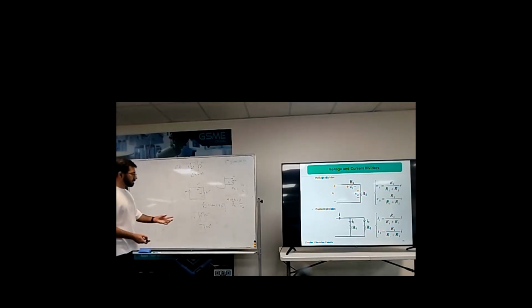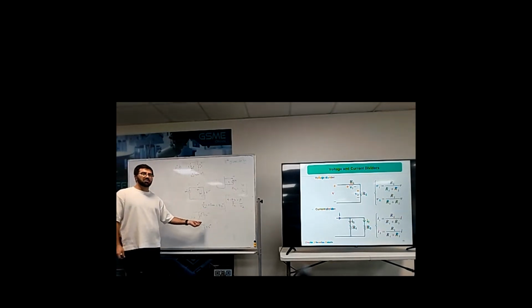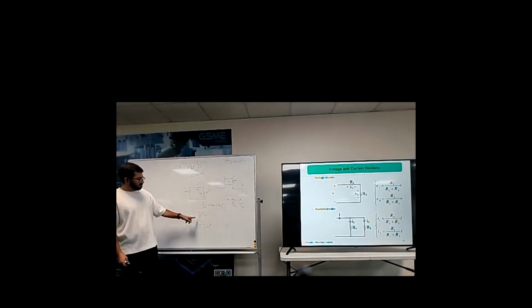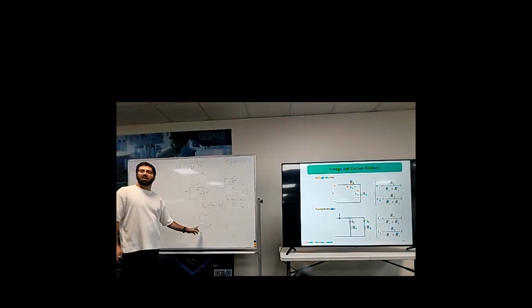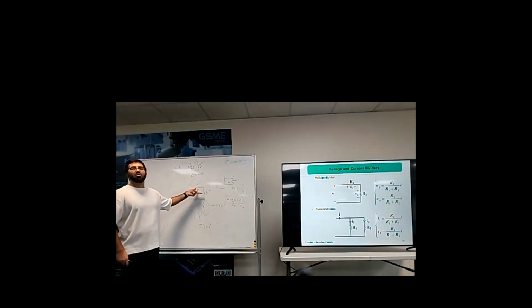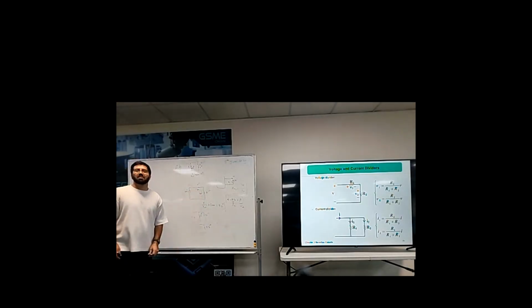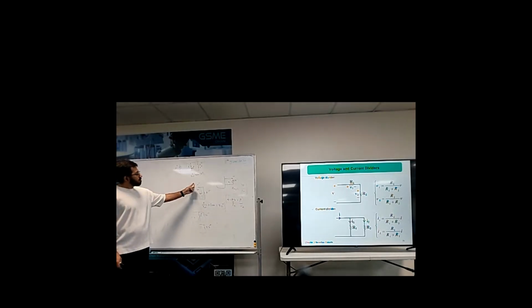The result should be smaller than both. When you calculate the exact value, it should be smaller than both. But when one of them is much bigger than the other one, for example, 10 times, we can consider the paralleling of these two is almost the smaller. How about when we have two resistors in series? The bigger one, yeah. Because the equivalent is the sum of them, and if one of them is 10 times bigger than the other one, the equivalent is the bigger resistor.